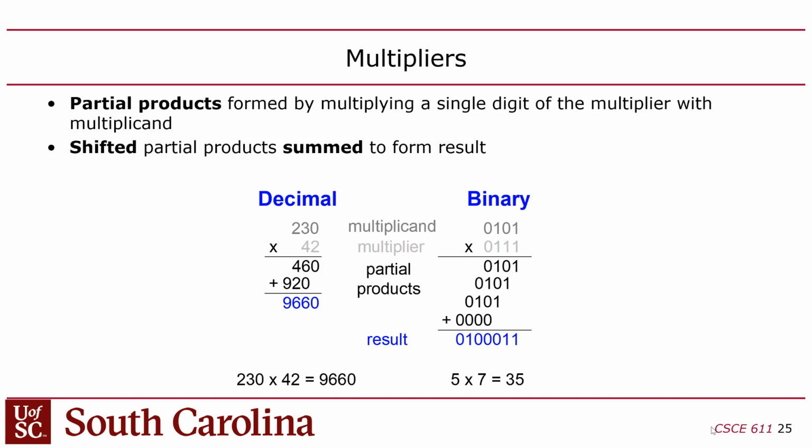You guys with me? So if I'm taking here 5 times 7, I'm going to say 5 is my multiplicand and 7 is my multiplier, and of course I could swap them if I want. So the fact that the multiplier is 7 and it has a 1 in the 0th, first, and second bit position, or bit 0, bit 1, and bit 2, that means that I take the multiplicand and I shift it by 0 bits, by 1 bit, and by 2 bits, and then just add those 3 things up.